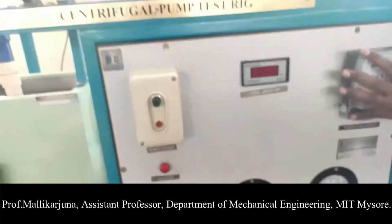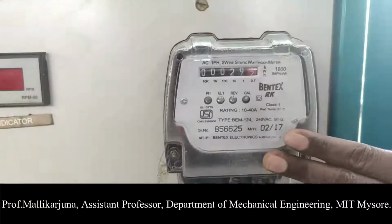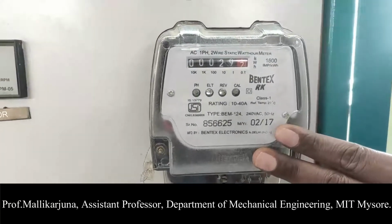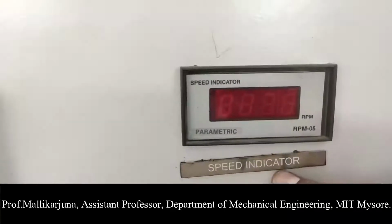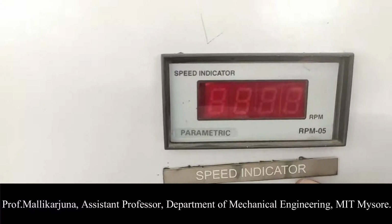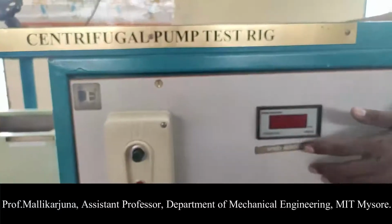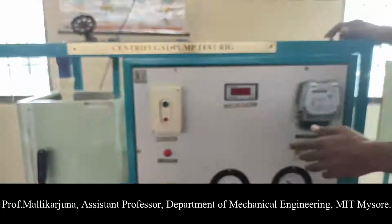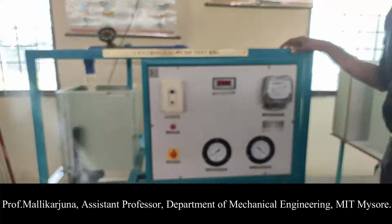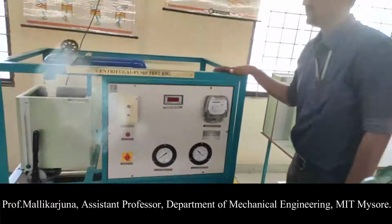Next, this is the energy meter. This energy meter is going to give us the energy that is supplied from the motor to the pump, and we have to measure the speed with which the belt drive is running. That has to be noted down here. This is sensed by the sensor which we have provided at the centrifugal pump side. So these are the various components that are present in the centrifugal pump test rig.